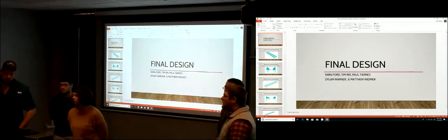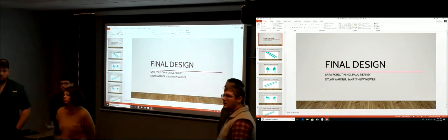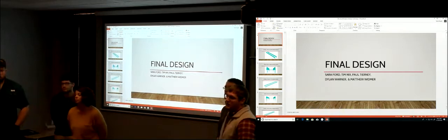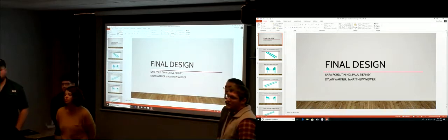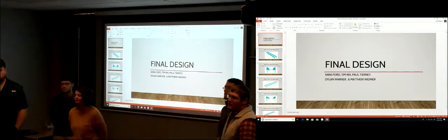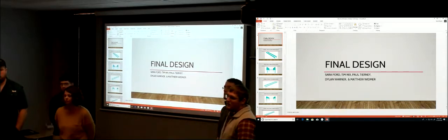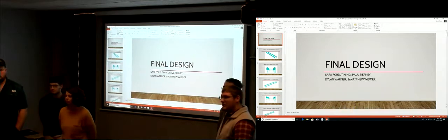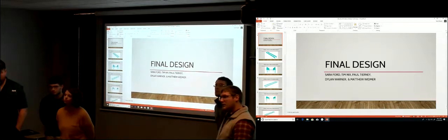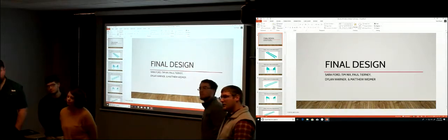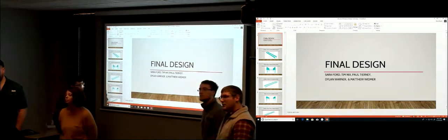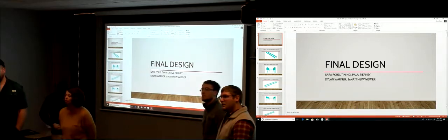Okay. And for Sarah, your design is good, but I don't know why you weren't able to get the weight down. I don't know why you have it 700 and something. I remember we talked about you have 2 plates right in the middle between the 2 members, right? And we said you don't need actually those 2 plates all over throughout the length of the bridge. So you actually can have this as a perforated plate. You have holes in it, large holes. That would decrease the weight.